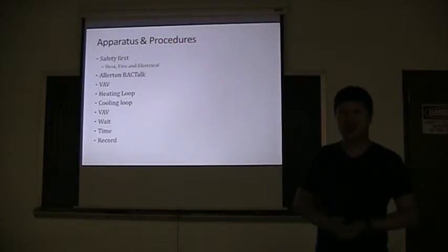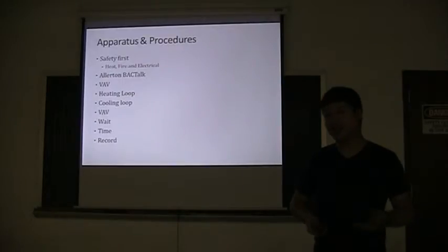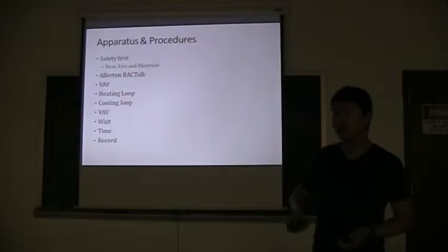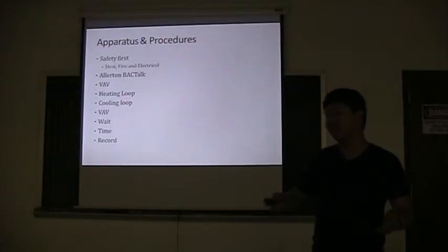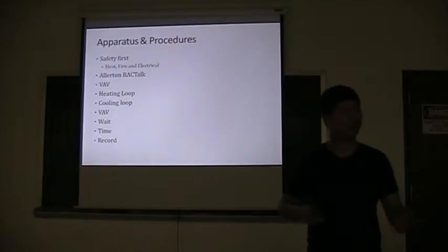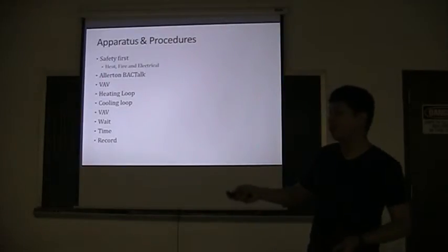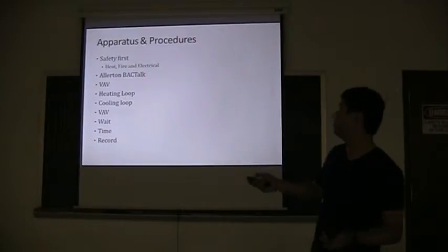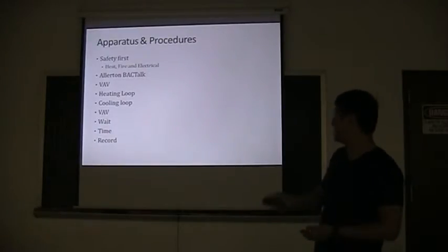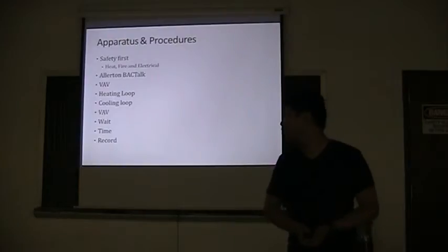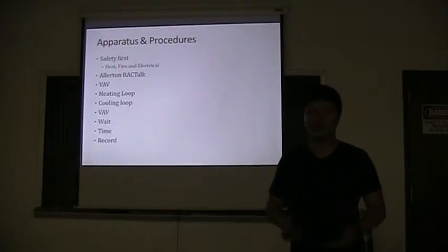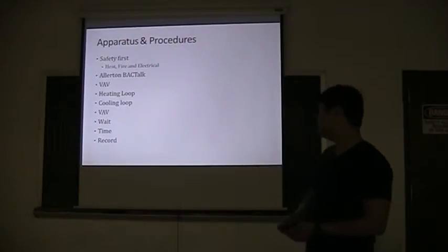So a little bit of the procedure. Well, first of all, safety first. Make sure you don't touch any ducts or insulation. You can burn yourself because they obviously get hot. Also, we don't want to turn on the heater before turning on the fan because we'll overheat the system and break something. And also know things like where the fire extinguisher is. I don't really see one in this room. I know the fire alarm's outside. There's a safety shower here. I hope nobody catches on fire. And then also stay clear of electrical components, just to avoid being shocked.